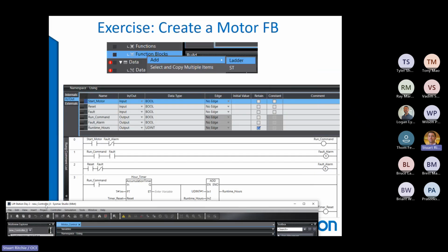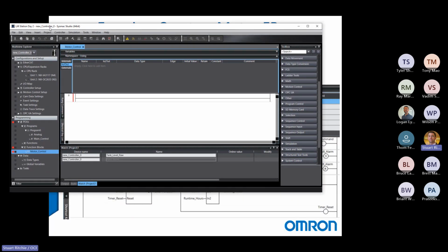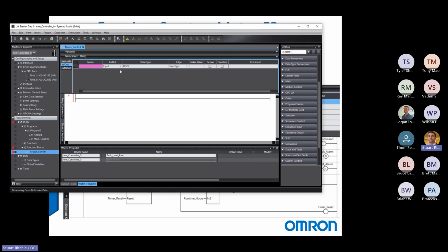From the PowerPoint, I mentioned that we will have 3 inputs and 2 outputs. So when we're configuring our function block, we will actually choose what that variable is. Is it an input or is it an output? There's also a category called in/out, which is essentially both an input and an output. We can read from it, we can write to it, and obviously we have to take precautions that we don't mess up the data integrity when we're doing that. So things like arrays and structures have to be in/out variables, but for elementary data types, input and output is all we need to use for that.